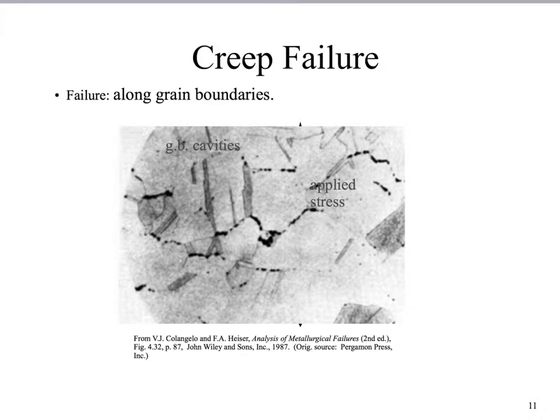So now that we've looked at the secondary portion of the creep strain rate graph, we can look at what happens microstructurally in the third portion, which is the tertiary portion of that graph, where we saw an acceleration of the creep strain rate up to the point of rupture. We mentioned before that during that time, a lot of stress concentrators start to gather in the material, like voids, cracks, cavities, and grain boundary separation.